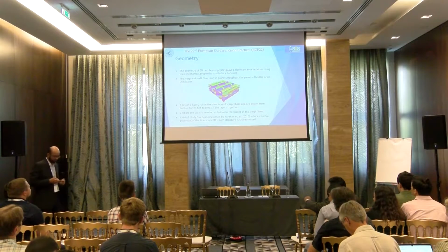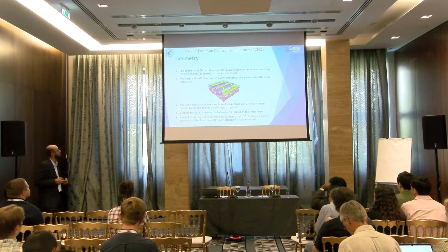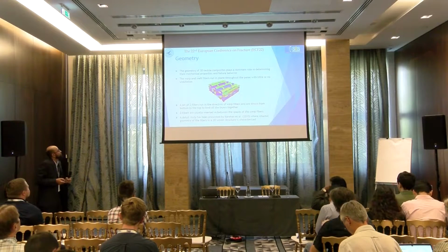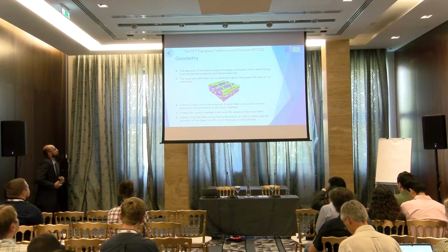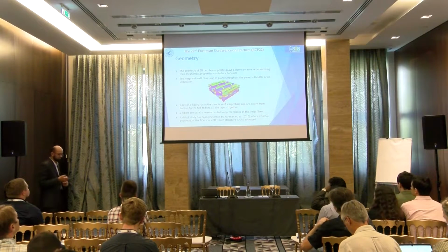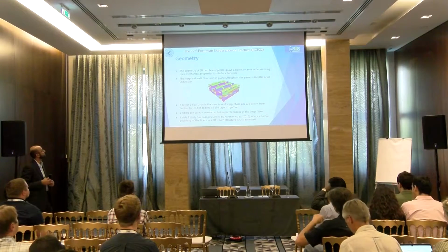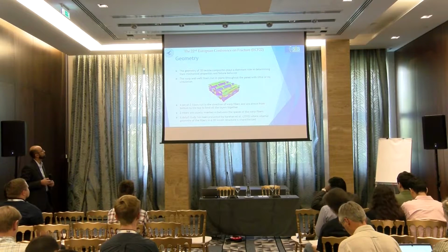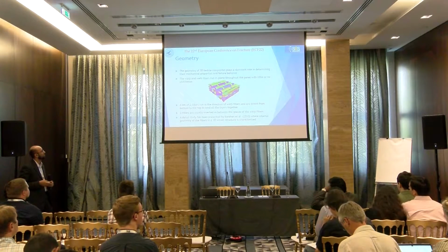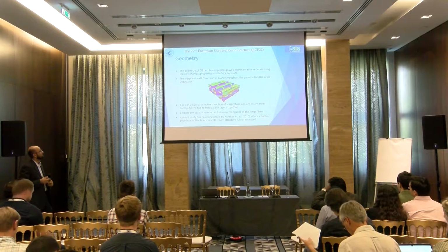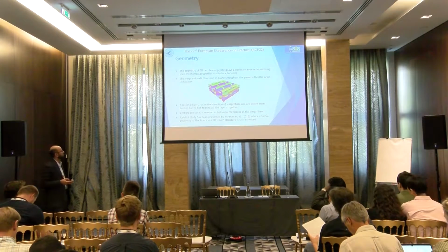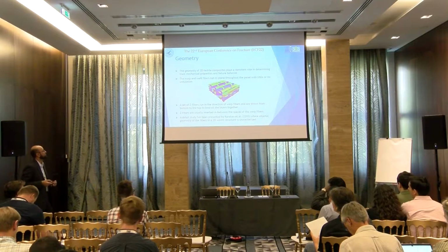At first, I will explain a little bit about the geometry. The geometry of the 3D weave plays a dominant role in determining its mechanical and strength properties. The warp and the weft fibers run in plane throughout the panel with little or no undulation. A set of Z fibers runs in the direction of the warp and is drawn from bottom to top.